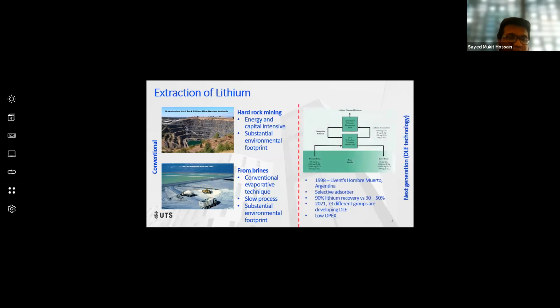However, the process we are interested in is the direct lithium extraction technique, or DLE in short. As the name suggests, instead of using evaporation, lithium is directly extracted from the brine while returning the water to its original source. It has several advantages over other methods, such as a smaller footprint, efficient recovery in a short time, and low operating costs. Broadly, there are three types of DLE methods: adsorption, ion exchange, and solvent extraction.